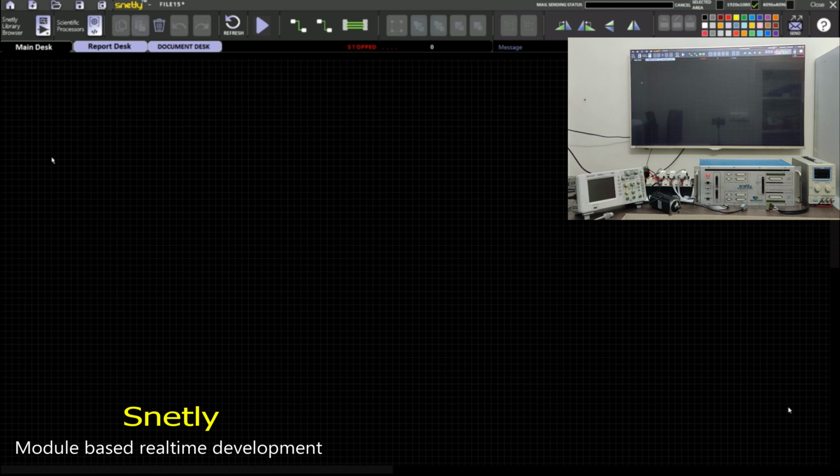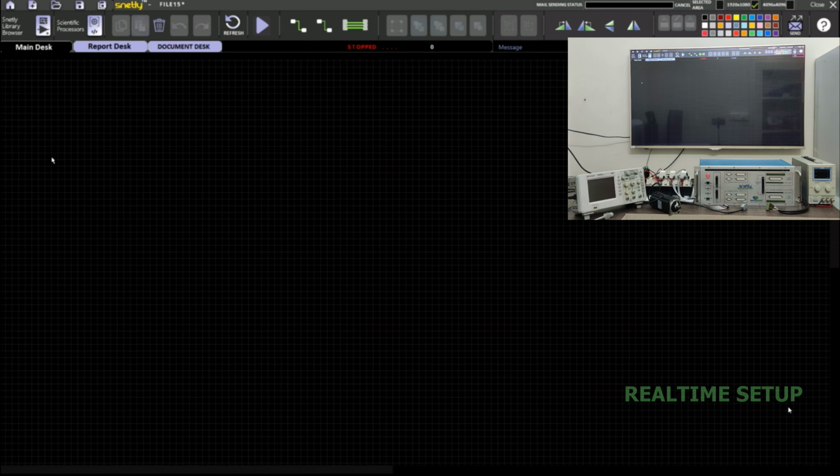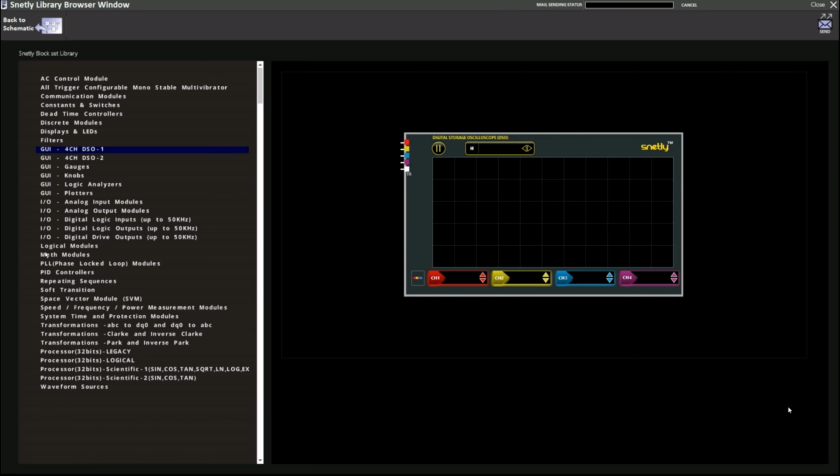First we need to connect our digital input. This kind of motor usually runs based on the motor feedback. Here in this motor we have Hall sensor feedback. Totally we have 3 Hall sensor signals in the motor feedback with a phase shift of 120 degrees. Based on this we need to excite our voltage source inverter module semiconductor switches so that the motor runs with the inverter module. Since this kind of motor is not a self-start motor, we require a voltage source inverter module to run the motor.